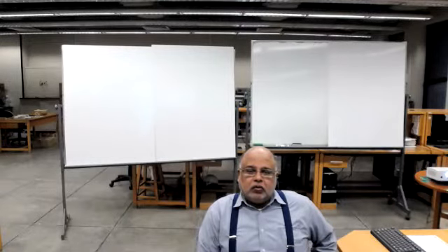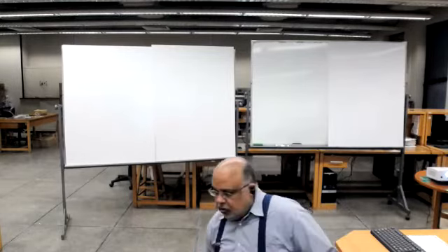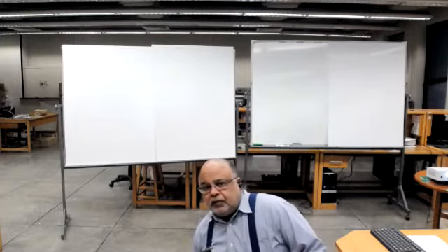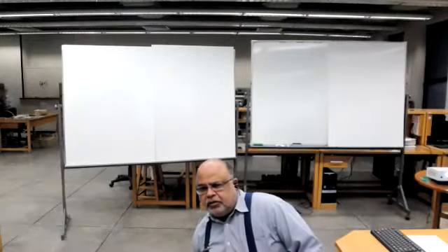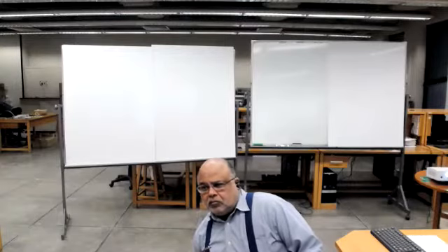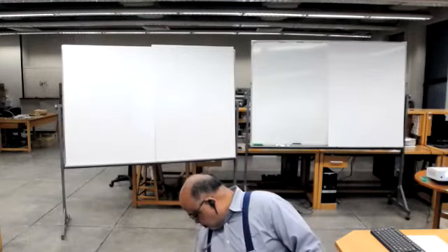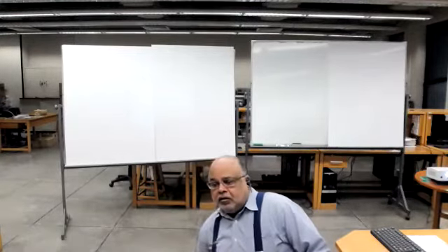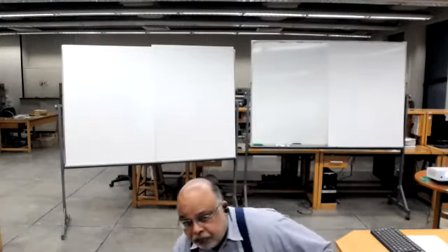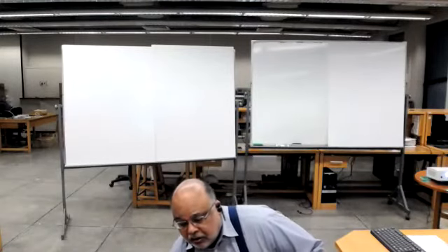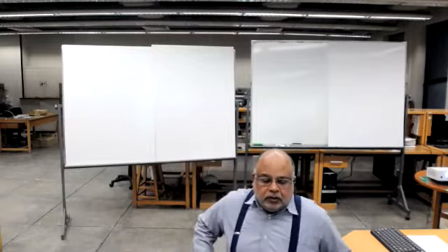So today we'll go beyond the sample and hold circuit into the actual ADC construction, how ADCs are constructed. Some important components of these ADCs are an AND gate, a DAC, a counter, maybe a state machine, things like that.